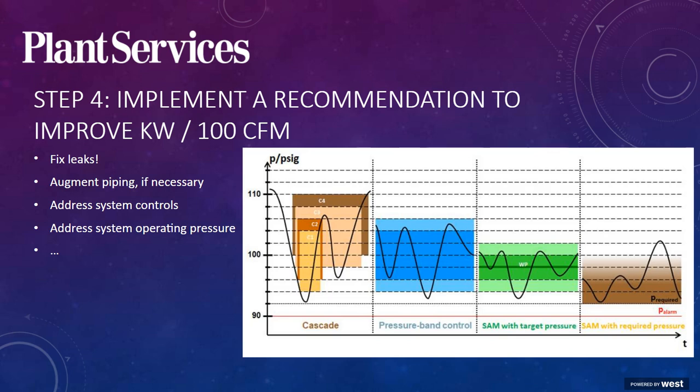Operating pressure, that can have a big impact on your overall bottom line. Reducing your air pressure to the lowest possible point, often referred to as the scream point, not only going to reduce your energy consumption, but will reduce your demands. If you put that pressure too low, you're going to have people in the plant screaming for more air, so hence, scream point. System pressure has a direct effect on energy consumption. You'll often hear 2 psi equals 1% energy increase, as well as 10 psi reduction can reduce 10% flow. So these represent significant savings opportunities.